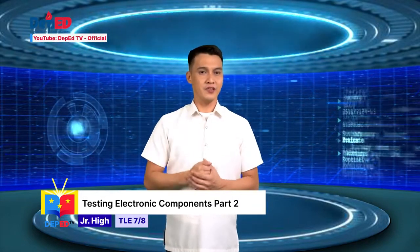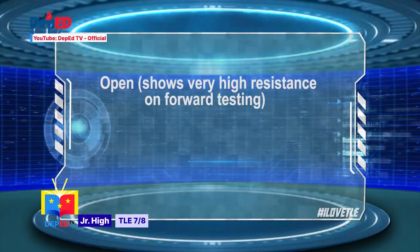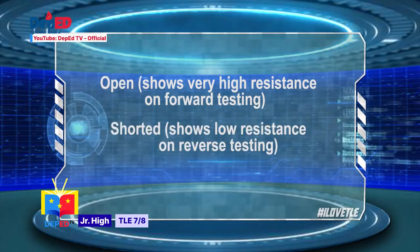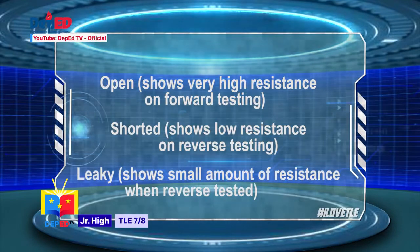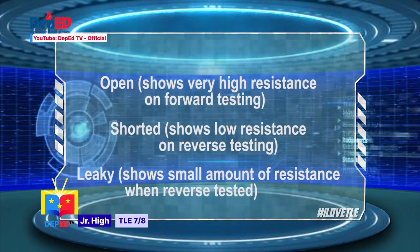The three possible defects that can occur in diodes are: open, shows very high resistance on forward testing; shorted, shows low resistance on reverse testing; and leaky, shows small amount of resistance when reverse tested.